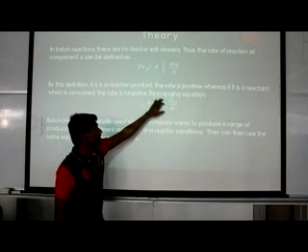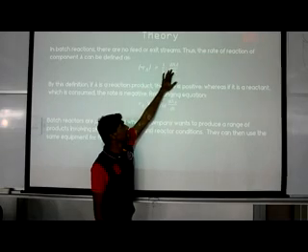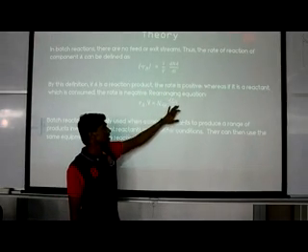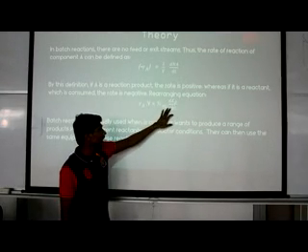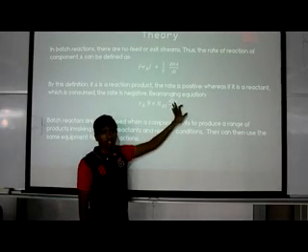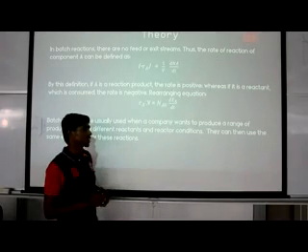As you can see here in this above equation, it is dNA over dt. So NA is equal to NA0 times XA. That is where we get this term here, and we bring out the NA0 as it is constant, and XA is the one that will be changing according to the reaction that we are carrying out in the reactor.